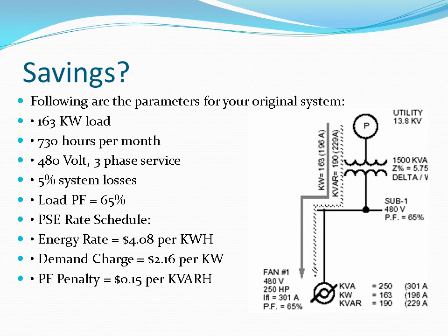After installing capacitors in our system, should we expect some savings? Yes, let's look through an example of how to figure this out. A calculation can be run to determine when this payoff will be. As an example, assume that a portion of your facility can be modeled as in the figure. Your current power factor is 0.65. The parameters for the system are as follows: